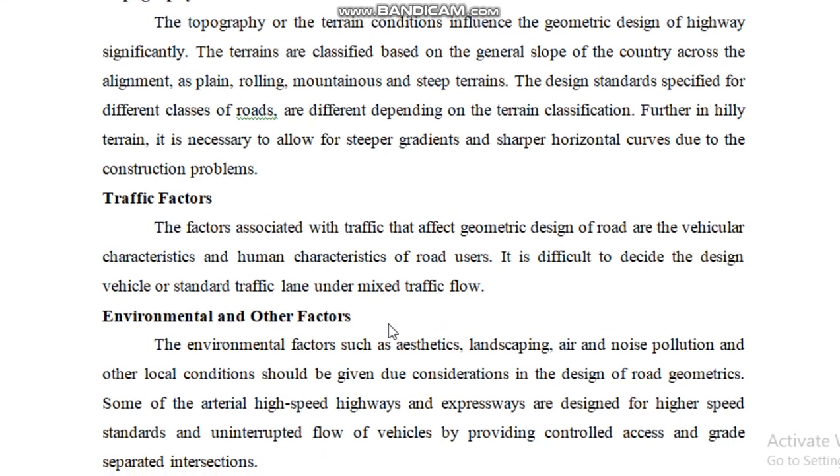Then traffic factors. Obviously, an increase in traffic will definitely need wider highways, meaning more carriageways, or in case you want to go for a limited number of carriageways, then at least a minimum or sufficient width carriageway needs to be designed so that the volume by capacity ratio will not go beyond 1.